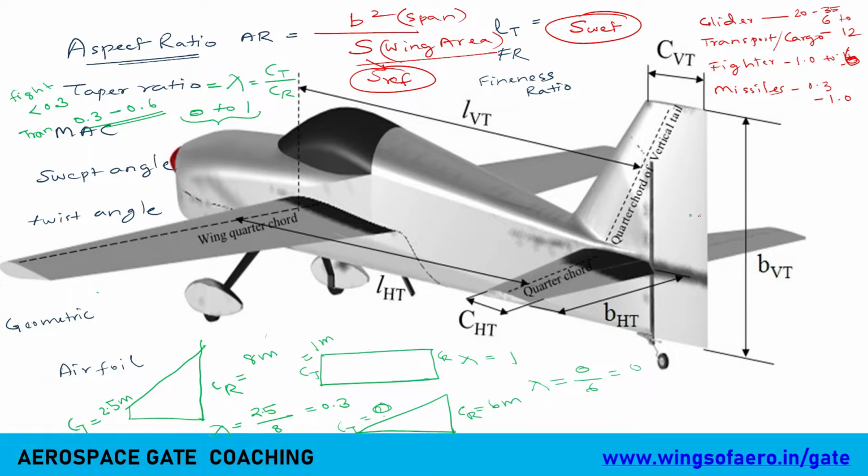Okay, so stalling, if I have to draw it graphically, this is angle of attack and this is CL. Now let's take a symmetric airfoil. As I increase the angle of attack, my lift is increasing, right? I reach a certain point of angle of attack. By further increase in angle of attack, my lift will fall drastically.